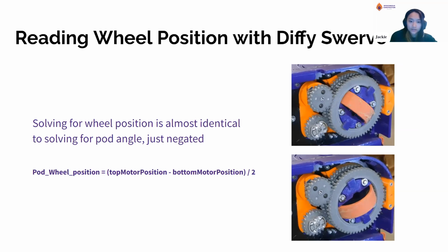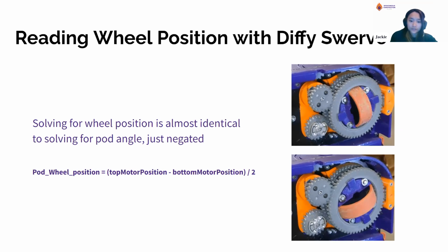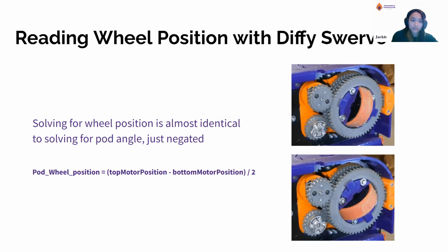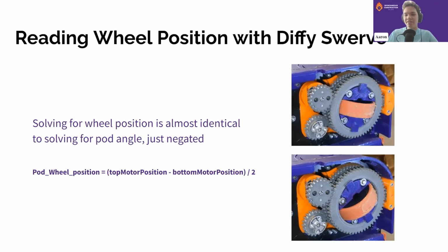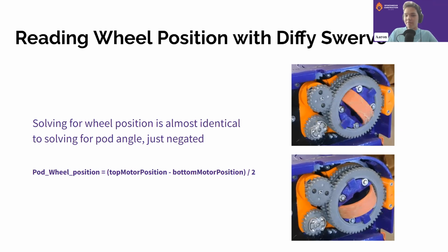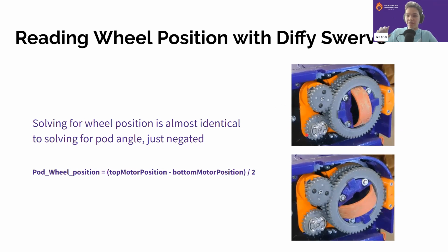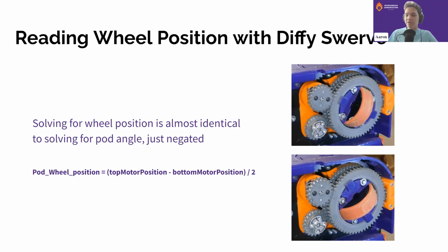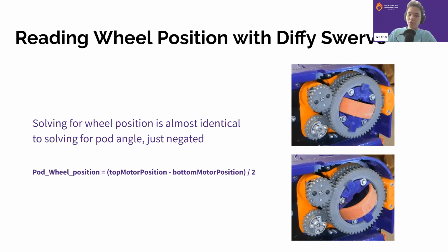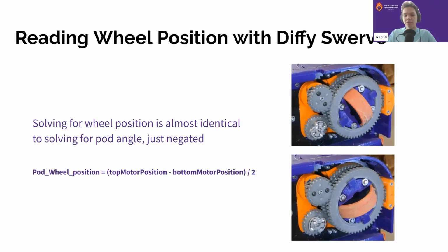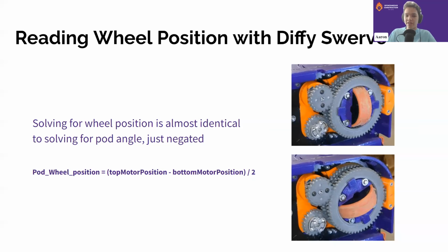We got a fantastic question where someone was asking, is the differential able to use servos for rotation, or is it only possible for coaxial? Yeah, that's the one I was just talking about, Jackie. Right, sorry. Just to reiterate in case it was missed, basically in a differential swerve drive, both sources of power have to be equivalent amounts of force for it to be able to turn and move properly, since both of them will be incorporated partially into the movement of the wheel and partially into movement of the pod. So you can use servos, I guess, for both of them, but just make sure that it's the same source, and DC motors are generally a lot better for that kind of thing.